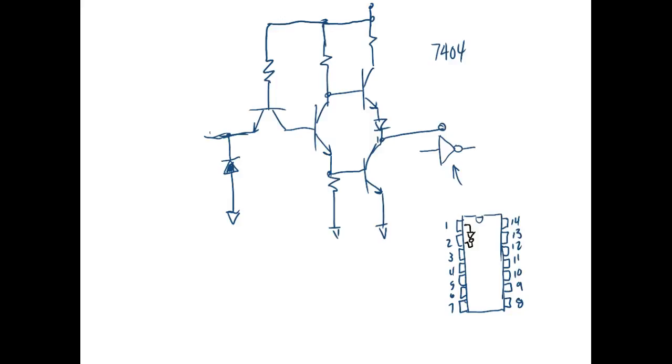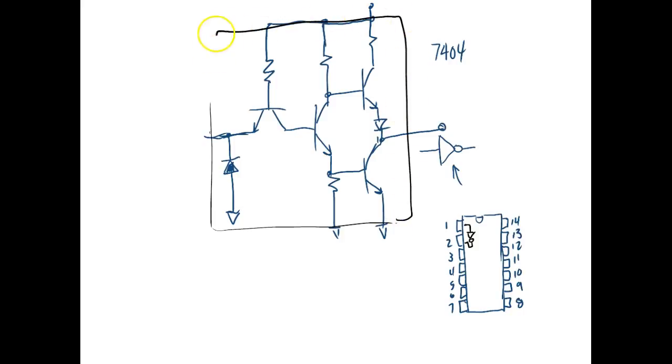Yeah, we have 12 connections, because we get the input and the output, and the power is shared inside the circuit. So that would be 6 inverters in here, right? And they're in there like this, if I can draw them. Then this pin right here they label ground, but it's actually the common. And then over here, they flip around and come around like this.